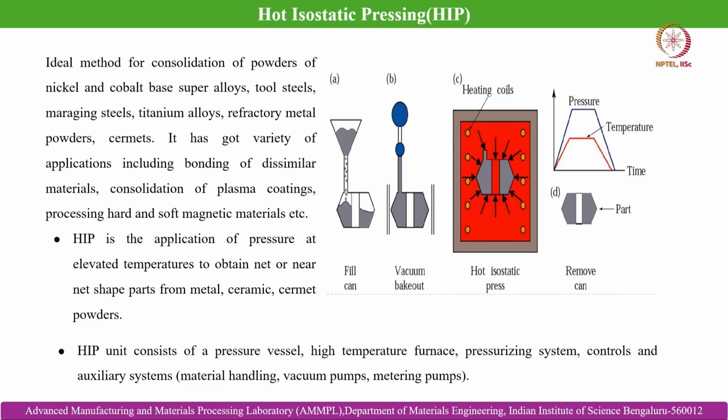It can yield properties better than the classical PM route of initial compact preparation via pressurization and subsequent thermally activated sintering process.